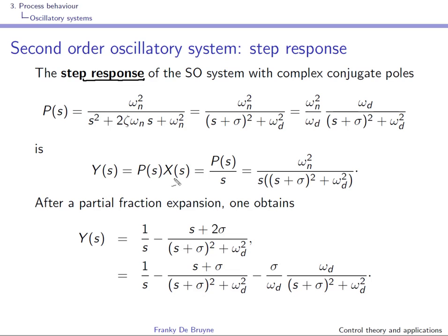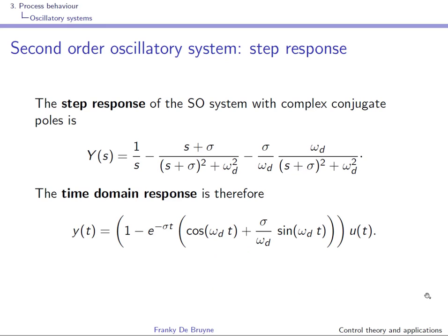You can of course also obtain the step response of this second order oscillatory system. Well, you have to take the transfer function and multiply by 1 over s. This is what you obtain, right? And to compute the inverse Laplace transform, you need to perform a partial fraction expansion, and this is what you obtain. What you can see here in this term is the Laplace transform of a cosine that has been frequency shifted, right? And this is the Laplace transform of a sine that has been frequency shifted.